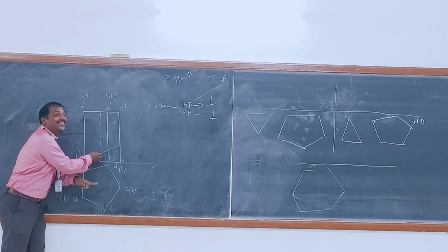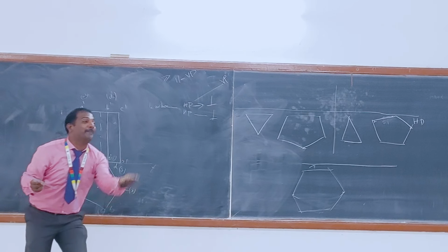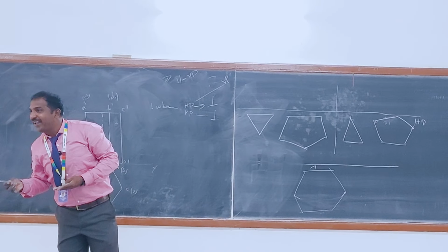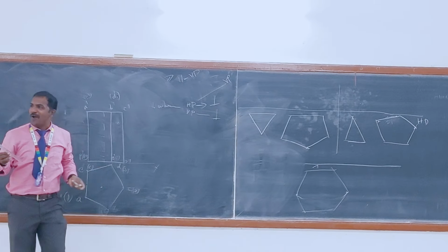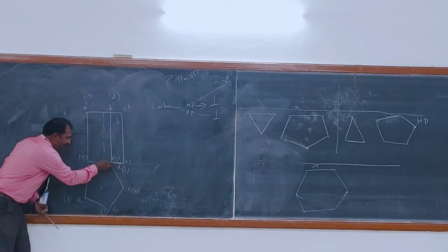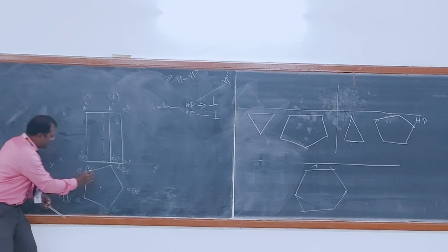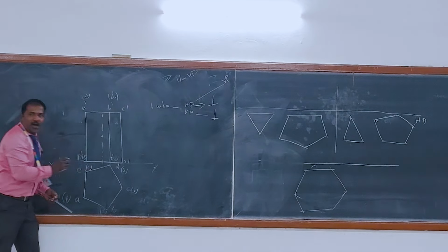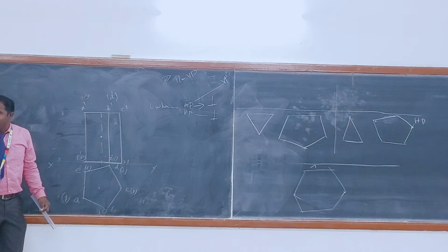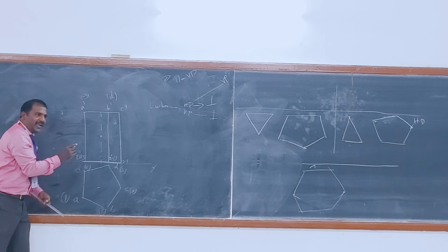And it meets the axis 30 mm from the base. Now it's fixed, right? Now I can draw the cutting plane. This is my base. From the base, take 30 mm, mark a point, draw one horizontal line, and place the protractor on that place.